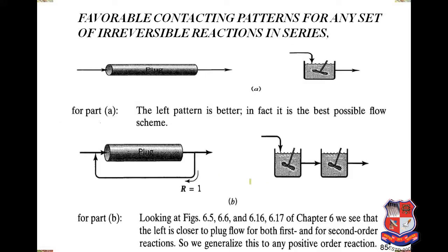Definitely in the coming few slides we are going to see this sentence in more detail. Now let's see the contacting patterns, which we have already seen in the previous chapters. In plug flow, no mixing is taking place, and as per the characteristics of the fluid the velocity profile is flat, whereas this other one is where 100% mixing is taking place. The left scheme is the best possible flow scheme for all kinetics-favorable reactions where the order of reaction is greater than 0.